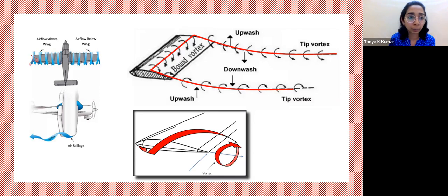Because of this, at the wing tips these two flows interact and a vortex is generated, which is seen here. Both of these are wingtips in this case, because if you imagine it not connected to a body, both of these tips have generation of vortices. This is because the flow above and the flow below interact at the tips. When it carries downstream, it forms a pattern of vortices that go like this, in the trail of the wing.